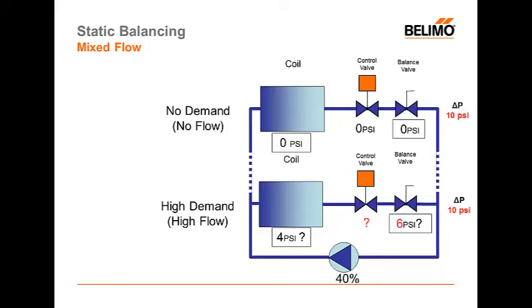So we have starved this coil because the balancing valve has overtaxed this line, or really it was statically balanced based on the fact that there was going to be 20 pounds in this loop, and currently there's only 10. So this can be very problematic. Balancing valves can create problems of overflowing all of our coils, but you can see another scenario here where we've caused a massive underflow that has starved this zone. Now, if we had utilized a pressure-independent valve or even a flow-limiting valve, for that matter, in this case, we would not have seen this particular type of problem.